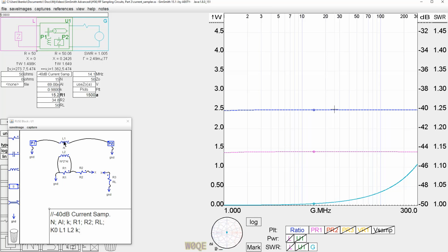We could monitor, say, from the center of this winding to the center of this winding, and since that's one turn, it's going to be hard to get in there and do that. It's easier on a drawing like this to put a capacitor between here and here, and we'll call that half the capacitance that we'd measure, and then we put the same capacitor again on the other side. So if we had a circuit that had, let's just use an example, 1 picofarad capacitance between one winding and the other winding, each of these would be a half a picofarad.